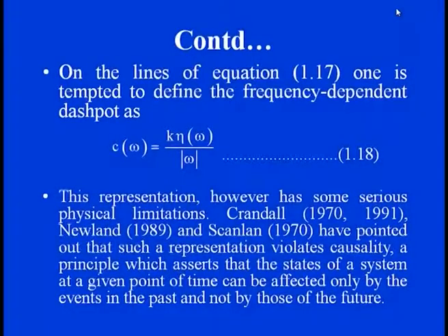But he clearly explained how we can make an approximation in those cases, and what the objections are in doing so. On that basis, we can say that the frequency dependent dashpot is C(omega) equal to k eta omega divided by modulus of omega.